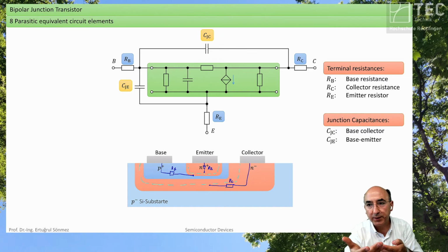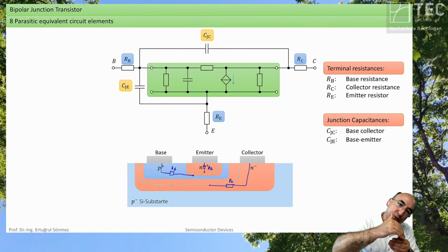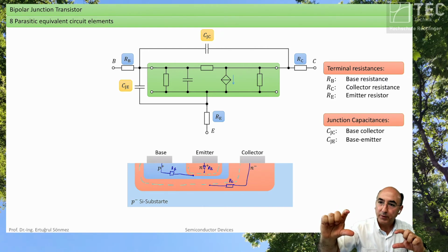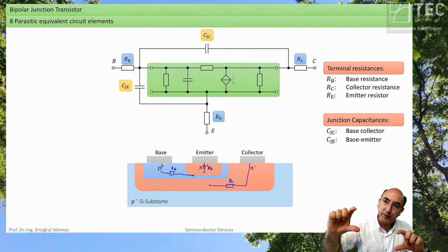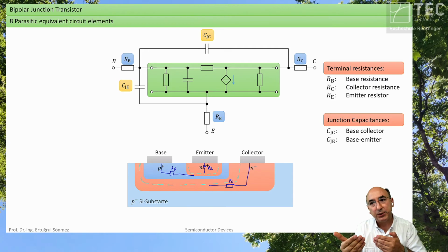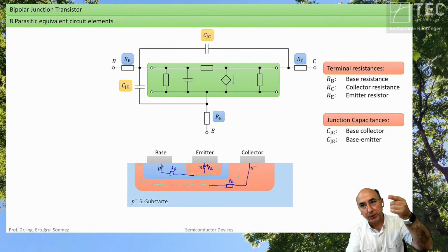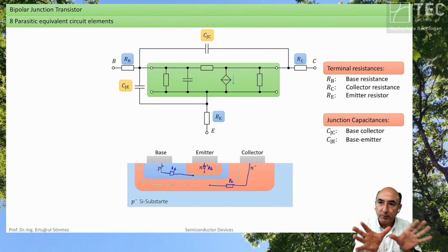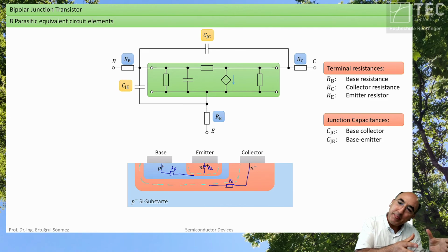It's an inversion layer. And if the band bending is twice the distance as before, then you have strong inversion. From these conditions we calculated charges, and from the charges, using the capacitance, the voltage. This voltage is the threshold voltage. So in these 3 minutes, you have learned the devices.